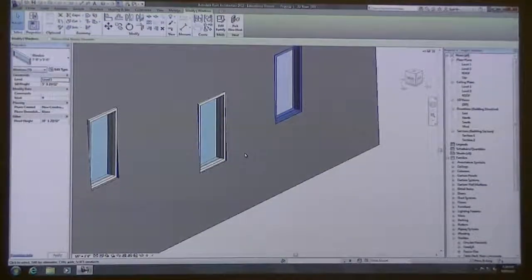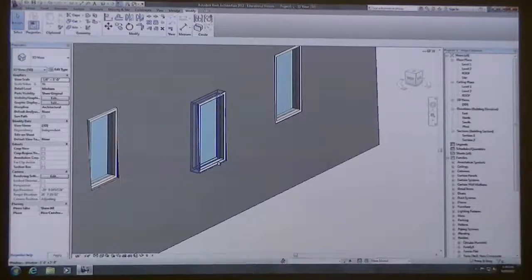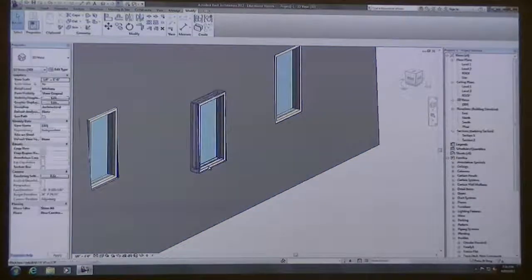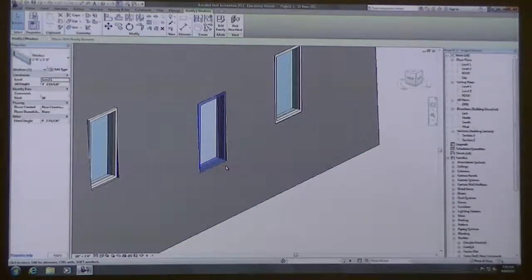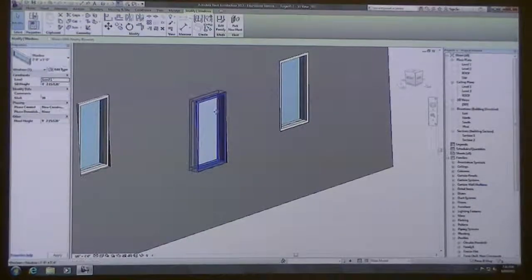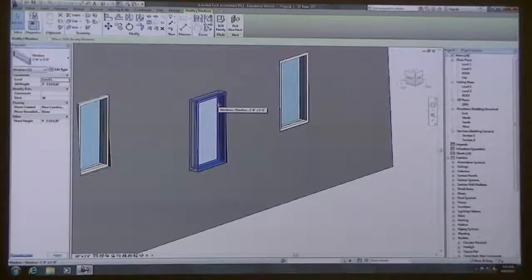It's not going to actually tilt the window. And there isn't really any kind of setting that we can establish that would tilt that window. I've seen some people actually model an angle into the extrusion as a parameter and then set that as a default, and you'd have to sit there and play with all that.